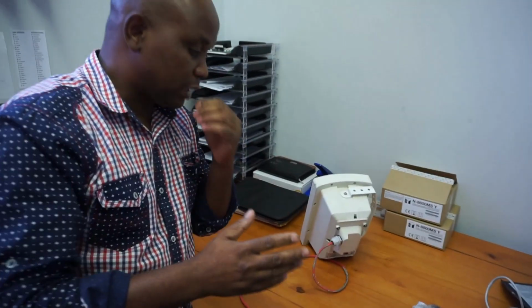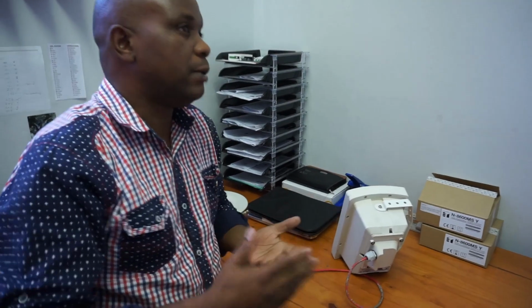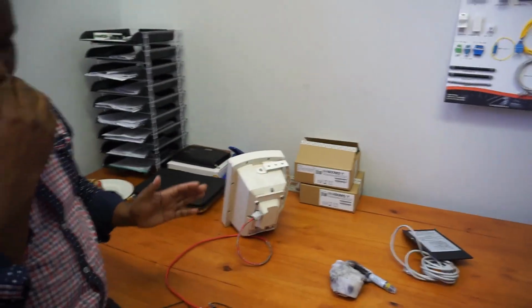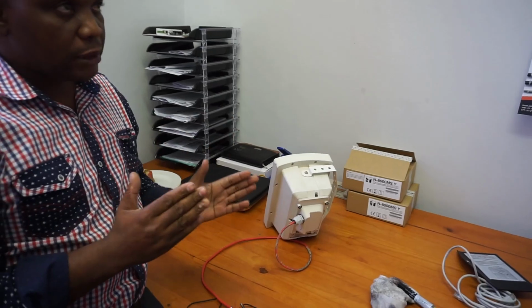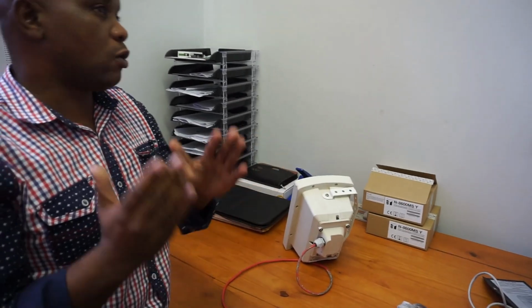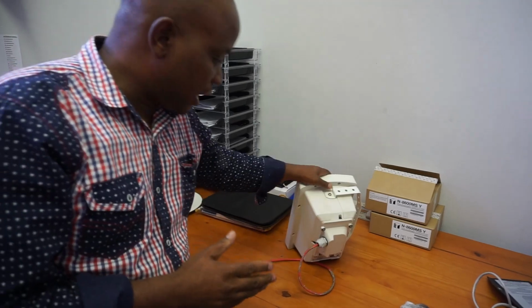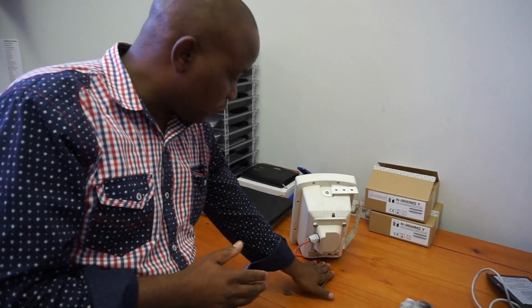So the times 1 scale works for few speakers, not a lot of speakers. The times 10 scale works with, I won't say average, but let's stick with a sort of average number of speakers. It's difficult to define the word average. Maybe 20, 30 speakers. But the times 100 is for a long speaker line with a lot of speakers connected to it. That's when you use the times 100 scale. So it basically depends on how many speakers you have and how long the cable run is.